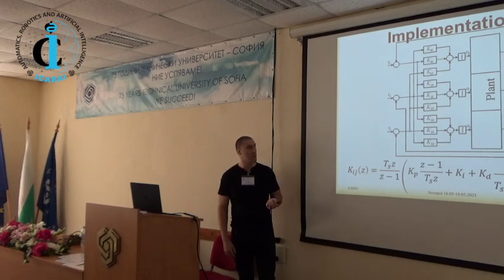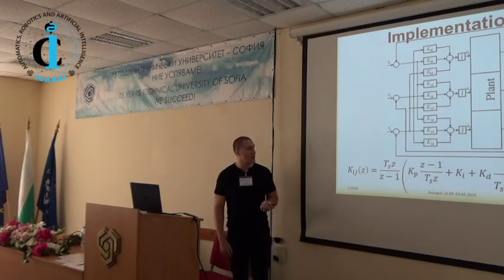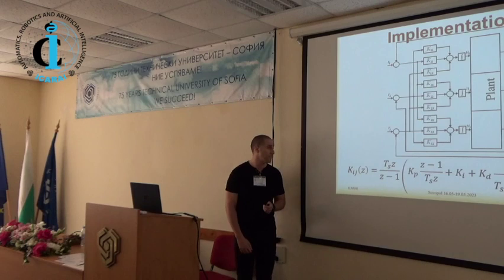For the implementation of the digital controllers themselves, the separate transfer functions, we use here the velocity form. Why? We would like to factorize the integral of every one of the 3 controllers in this way, so it would be simpler to use some techniques for anti-windup. In our particular case, we quantize the integral part when we hit the saturation limit.